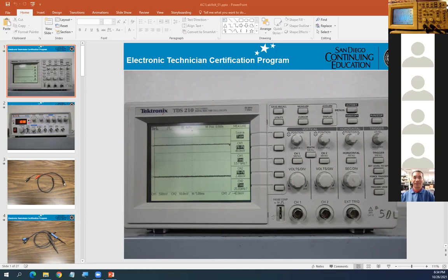you must use both channels. Channel 1 connects to A, channel 2 connects to B. That means you need both channels. But Mr. Pham, do you still have to have both of those black leads going to ground? Exactly. The scope grounds must be on the black one.